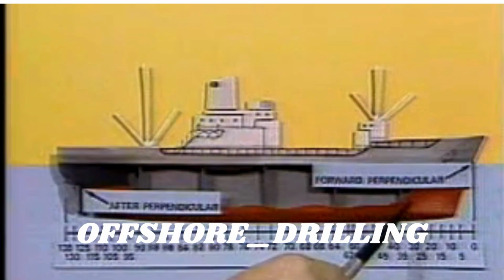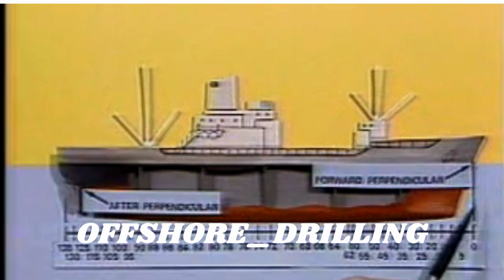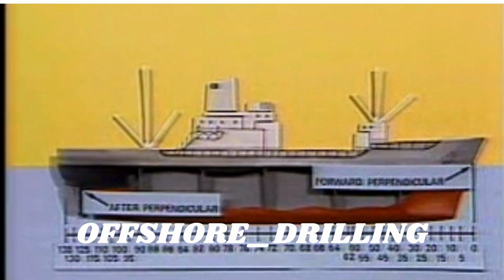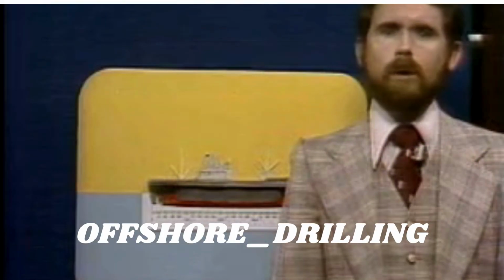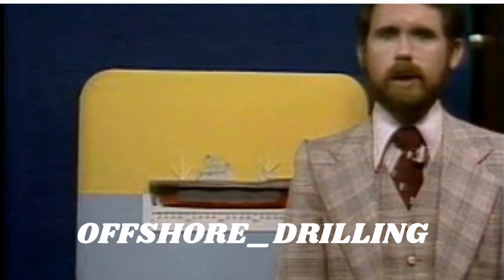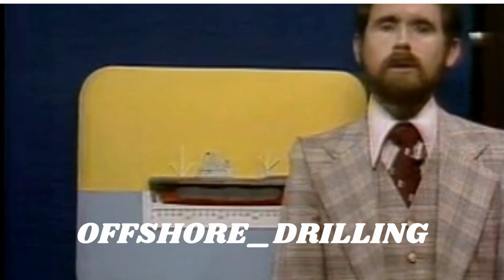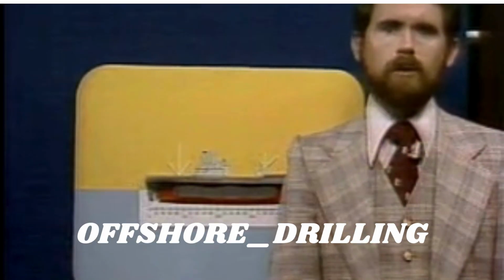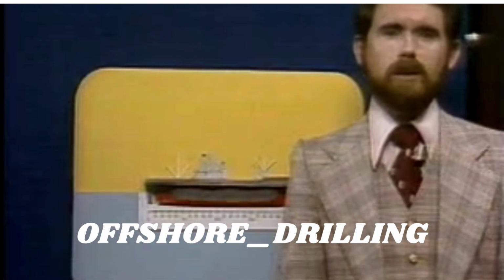The frames on a ship are usually numbered from forward to aft, and frame number 0 can usually be found at the forward perpendicular. You should refer to the ship's plans to see which system was used on your vessel. One other type of problem that we frequently find on license exams is to solve for location of the longitudinal center of gravity, LCG. The procedure is similar to solving for vertical center of gravity, except that the reference point is the forward perpendicular instead of the keel.